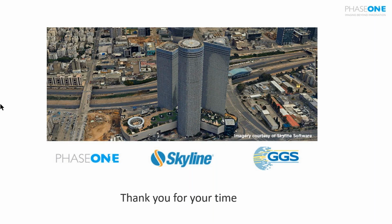If it's above 3/4 of a pixel, if you're getting an average residual of 1 pixel or more, the mesh might not be very crisp or very clean. There are things in the software you can do to generalize or smooth it, but it's not going to be as accurate a 3D product. So I would say 1/2 pixel or better, which is usually achieved through automation in the PhotoMesh aerial triangulation suite.